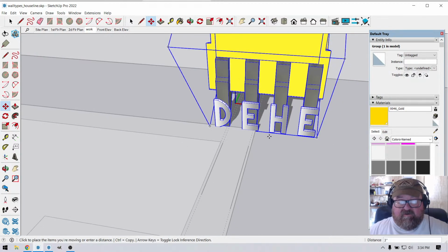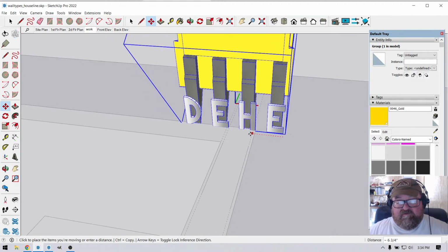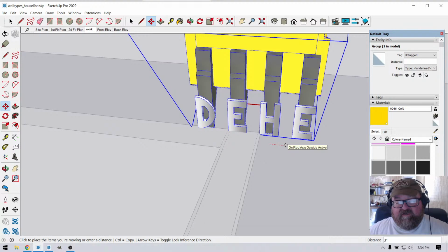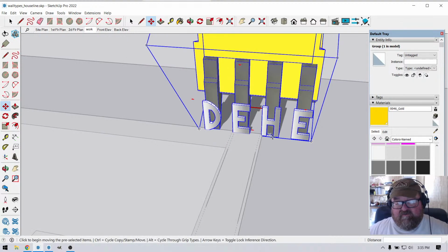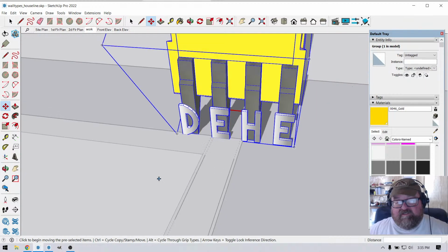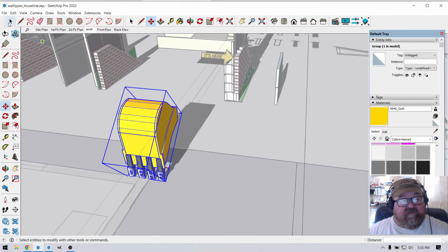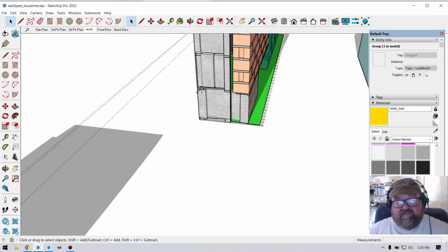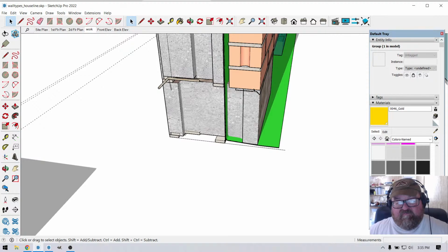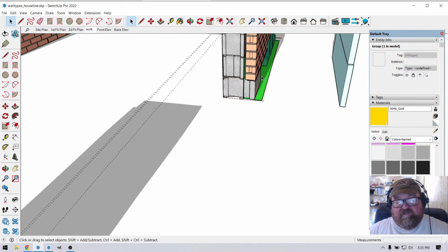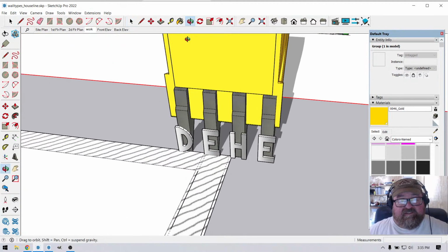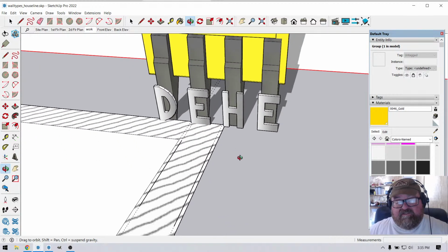So, he'll say, do you want to do 1 tooth or 2 tooth or 3 tooth? Somewhere you want to get a good 6 or 8 inches, especially if you have brick. If you have brick, you got to go wider, right? Because they're going to lay that 12-inch course of brick, right? So the house line is always here. But if we're going to have a brick ledge, you gotta dig outside the line, the house line. When we say dig outside the line, we're talking about the house line.